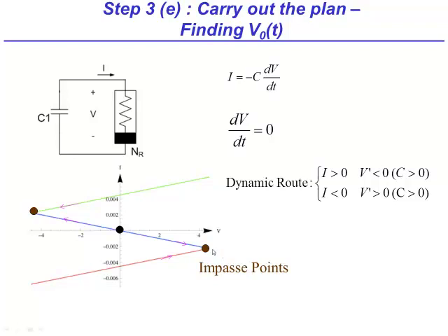Therefore, what the circuit does is it switches state along lines of constant voltage because V is the voltage across a capacitor and it cannot change instantaneously. In other words, as the circuit switches between the two saturation regions, V0 oscillates between plus or minus 9 volts.